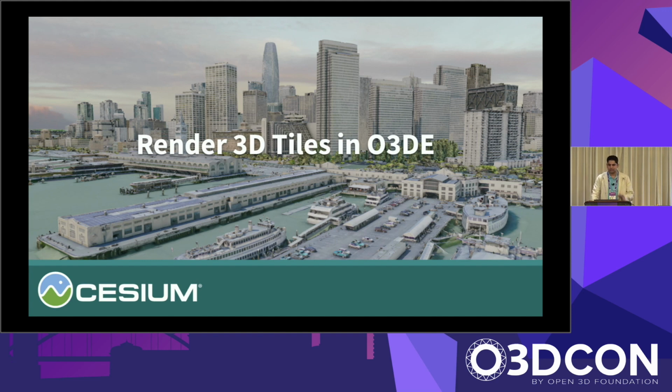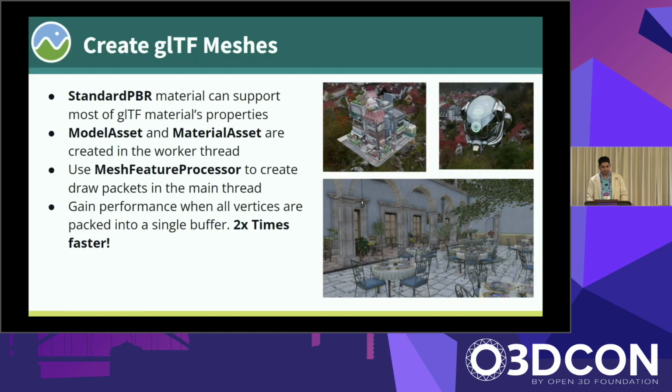So let's talk a little bit and dive into how we've integrated 3D tiles into O3D itself. The first part is let's get glTF rendering using the streaming part. So we're not even talking about 3D tiles here. Let's get glTF working. And the great thing is that O3D already has all the material support for glTF. The standard PBR material properties are all supported, which had a tremendous benefit when we started working with it.